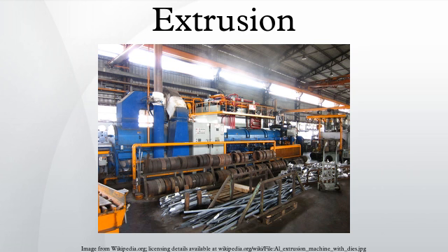Accumulator water drives are more expensive and larger than direct drive oil presses, and they lose about 10% of their pressure over the stroke, but they are much faster, up to 380 mm per second. Because of this they are used when extruding steel. They are also used on materials that must be heated to very hot temperatures for safety reasons. Hydrostatic extrusion presses usually use castor oil at pressure up to 1400 MPa. Castor oil is used because it has good lubricity and high pressure properties.